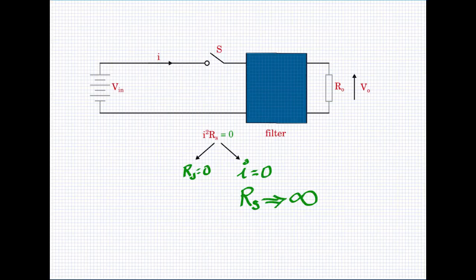It could have an inductor, and a capacitance. These L and C together would form a second order filter, and this chopper, switch plus the filter together will provide a DC voltage at V0, and together they form a switched mode DC-DC converter.